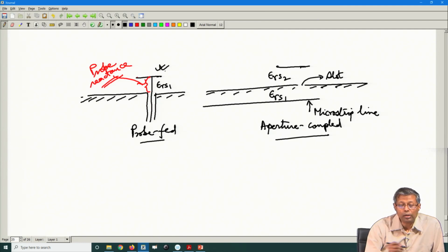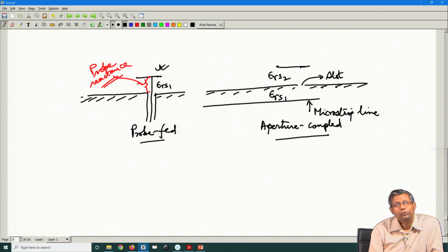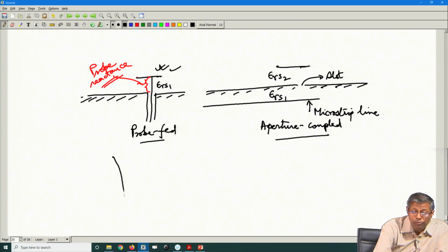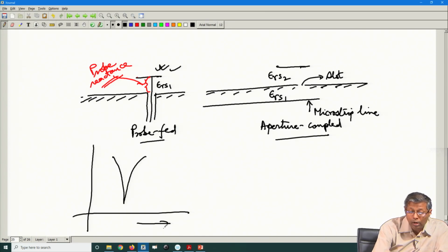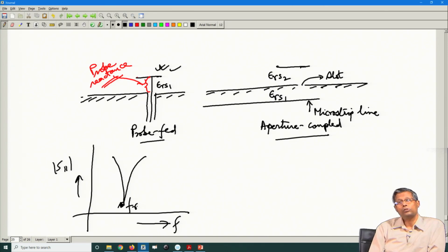we will talk about this one as we were talking, that your probe reactance is going to cause a shift from the source free resonance. So, your source free resonance is what you identify, that this is the resonant frequency I want to design this patch in. But when you actually design the patch, due to the presence of this probe reactance, your resonance frequency, that is the frequency at which the S11 is giving you a dip, this Fr is going to shift from the source free resonance frequency.